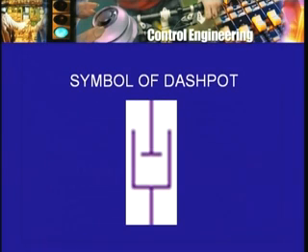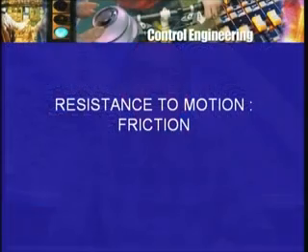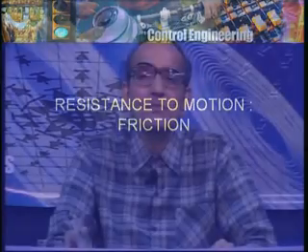So that's the spring of the mechanical system. The third thing is the dashpot, with the symbol that we have seen already. Now one may not come across a dashpot very commonly as an explicit component, simply because what the dashpot does is to be found without really asking for it. The dashpot is based on the idea of resistance to motion, but of a different kind from F equal to ma, the force of inertia, so to speak.